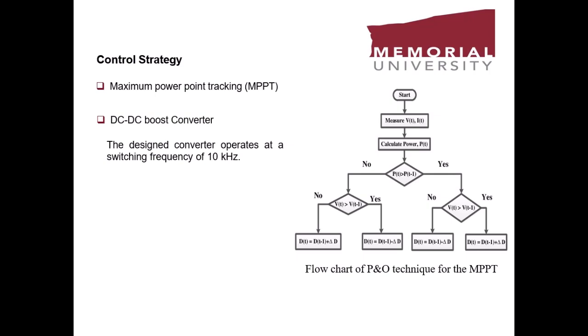In this slide, I plan to explain the control strategy. The MPPT controller regulates voltage and current to maintain optimal PV performance. The battery power adjusts in response to excess or insufficient generated power. Besides that, when the load demand is lower than the combined output of the wind turbine, PV system, or diesel generator, the battery charges, causing an increase in its output power and current.